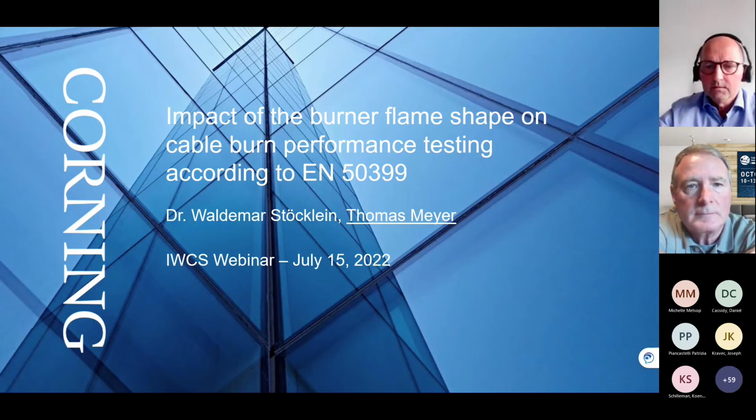I would recommend to use the method if there are any changes, like maintenance, a change in the gas supply, burner cleaning, or calibration. This method should definitely be used to get more evidence on flame shape variations. Every laboratory should gather its own experience by using the method.